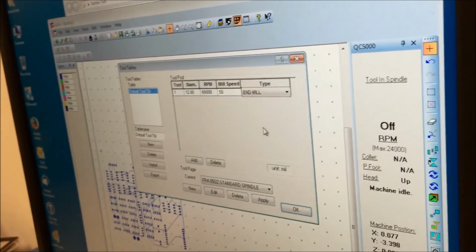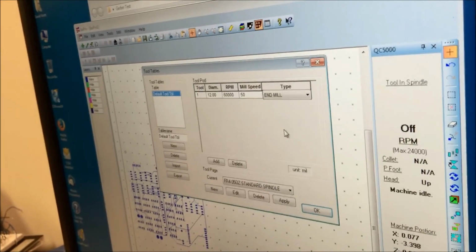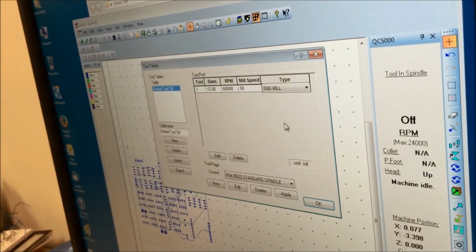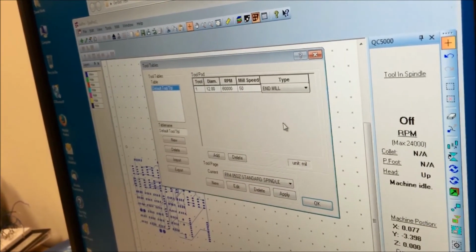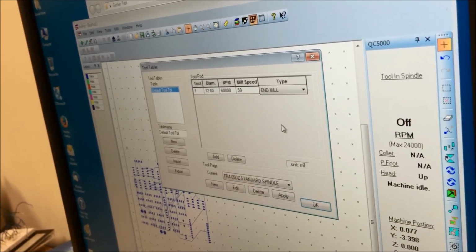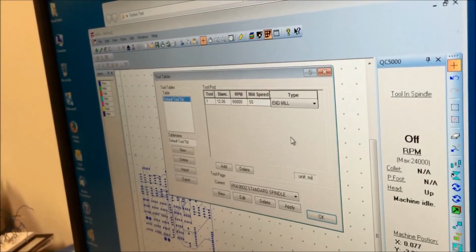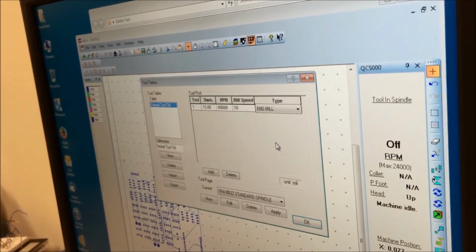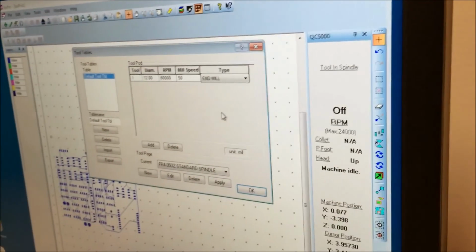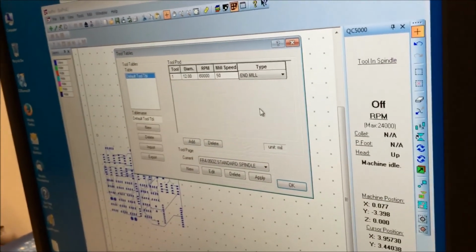Actually, that's something that I know that functionality exists. There's something called a tolerance check that you can do in this program, where when you have your tool table defined, each layer has its own tooling already defined, and same thing with the drill layers. I haven't actually done that myself, but I know that the functionality is there, that it'll run through the whole design and tell you whether or not your tooling actually makes sense. I know that's called tolerance check. I haven't actually been able to do that myself yet.